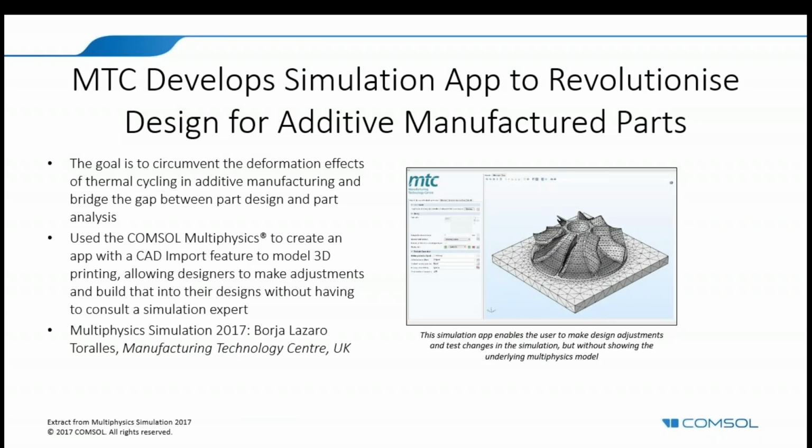This is a story that the manufacturing technology wrote for us, which is related to manufacturing. They have used COMSOL Multiphysics along with the Application Builder to use simulations to develop and optimize an additive manufacturing process. Now, the simulation here combines changing geometry, heat transfer, and solid mechanics to predict the residual stress and the deformation in a finished part that has been manufactured using something similar to a 3D printing process. So the part is built up in layers, and this process can lead to deformation of the final part, which of course is something that's unwanted.